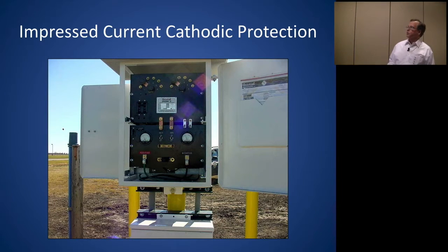If you don't have enough voltage, we can do what's called impressed current. Basically, we put a battery in series with our circuit and drive the voltage. This is a step-down transformer right here. You can take 120, 240 volt, three-phase voltage, step it down to get DC output. It runs it through a set of diodes and resistors. And you can regulate the voltage to whatever you want to drive as much current as you want. You kind of change the anodes, but it's another way of doing it.